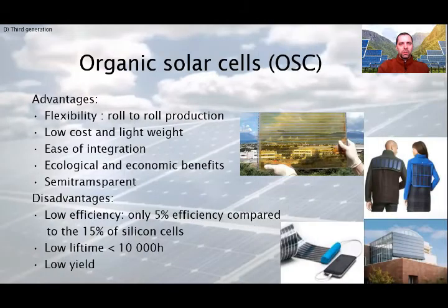Let's see the pros and cons of them. Advantages: flexibility, roll-to-roll production, low cost and lightweight, ease of integration, ecological and economic benefits. It is semi-transparent. Disadvantages are low efficiency. It has only 5% efficiency compared to the 15% of silicon cells. It has low lifetime, less than 10,000 hours, and it has low yield.